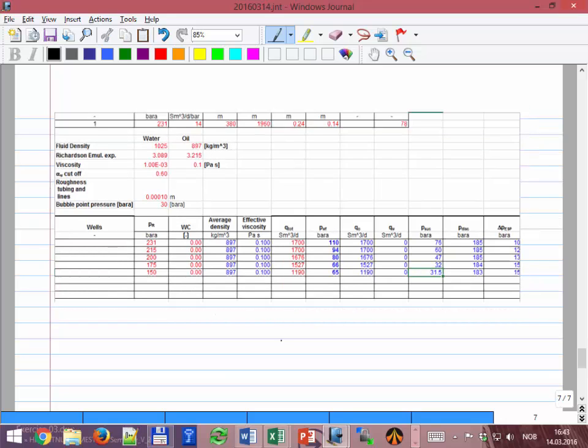Okay, we're going to say actually that after this pressure you won't be able to sustain 1700 anymore, and that's because of the pump power capacity. In this case you can actually do something. You can try to install a bigger pump, or buy a higher capacity pump if it can fit. So here you can do something, but after that the problem that comes in this reservoir pressure is that already the suction pressure is reaching the lower limit of 31.5. So here there is really nothing to do.